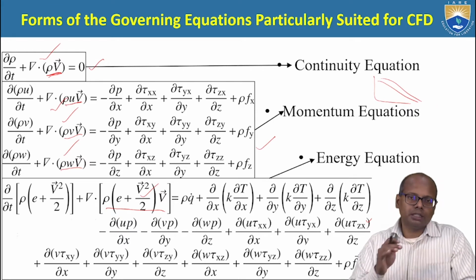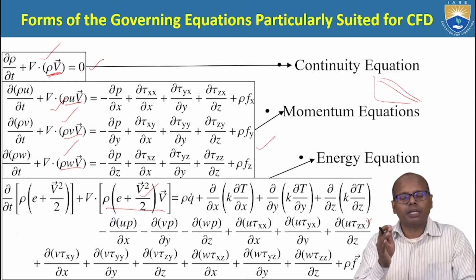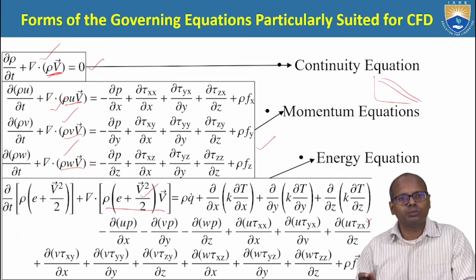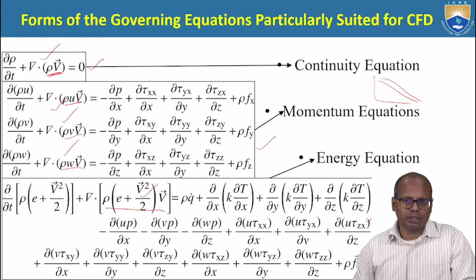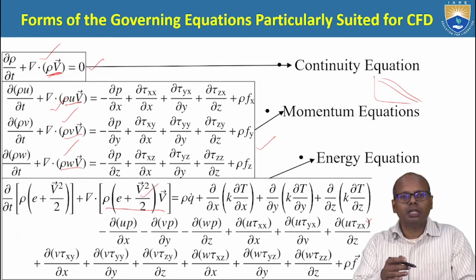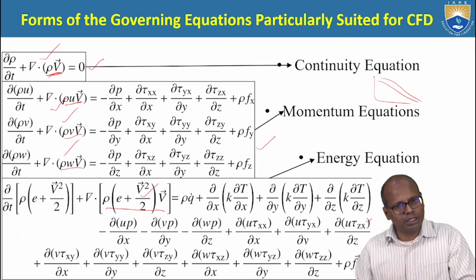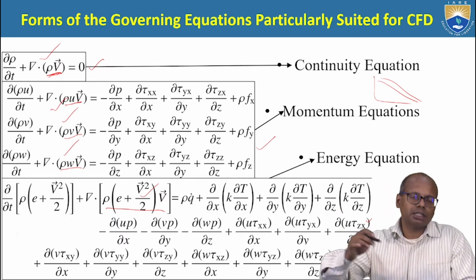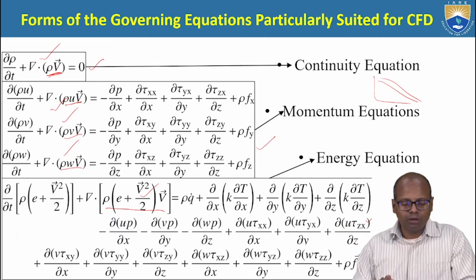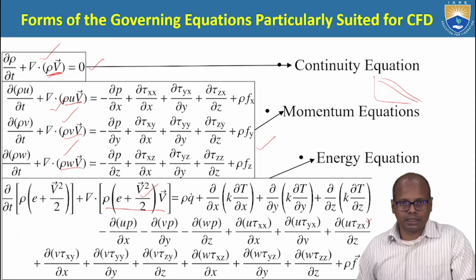In this graph it shows step by step in what fashion the error is progressing, whether it is converging, which means it is reducing, or whether it is increasing. Increasing means diverging. So this is the primary interest for us while solving the governing equations using a CFD program.